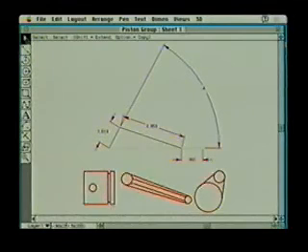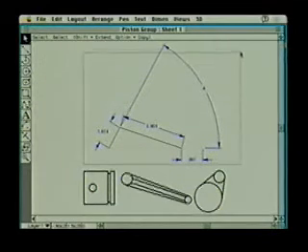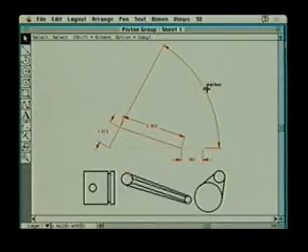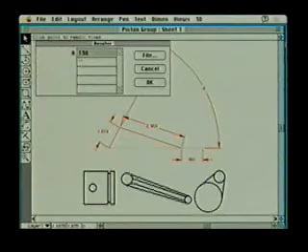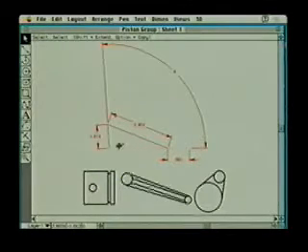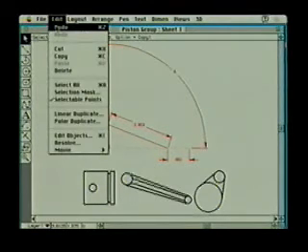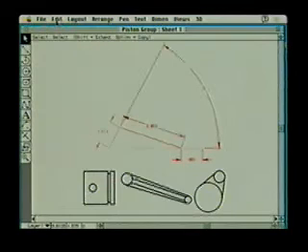What we're going to do here is generate a little shape, and we've got a triangle here. Ignore the things at the bottom for a moment and focus on this triangle. This is a parametric shape that has a variable A. We can resolve this variable A and resolve the shape by typing in some value like 94, some number you might want this angle to be. Fix it at this point and say OK, and it reshapes the triangle based on whatever you typed in here.